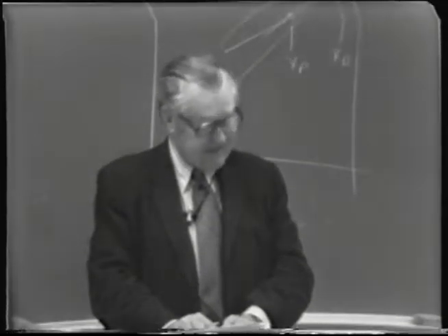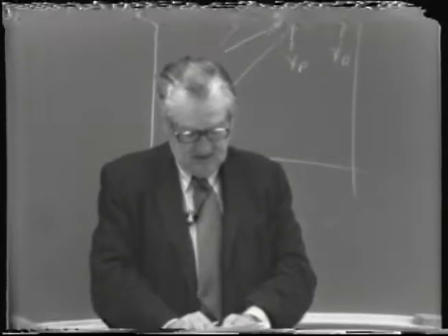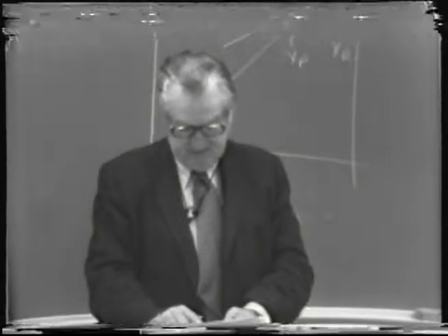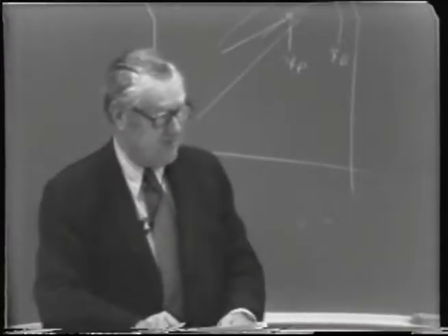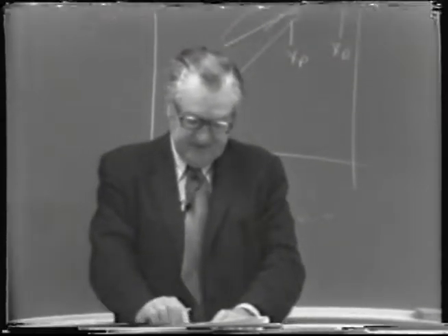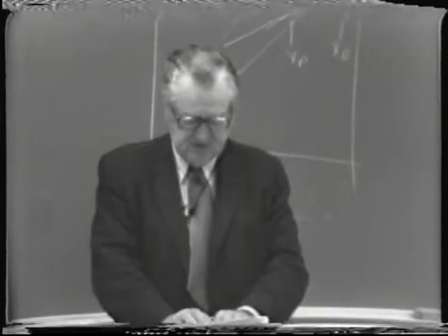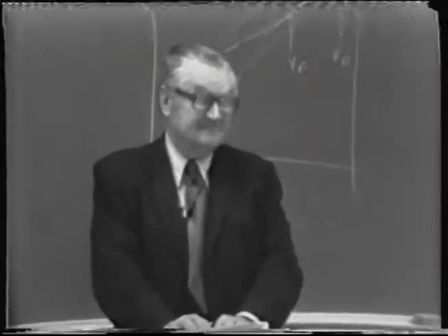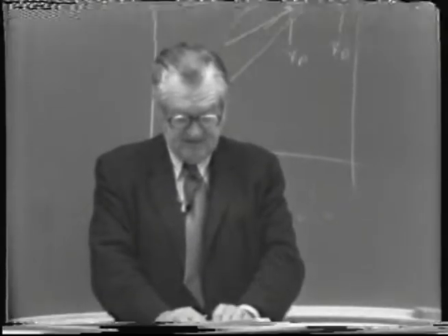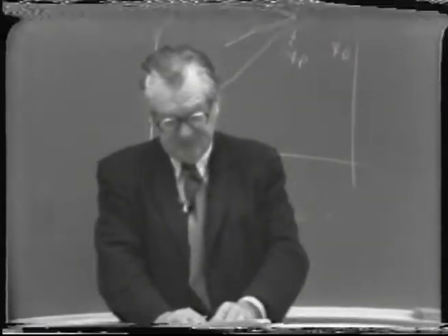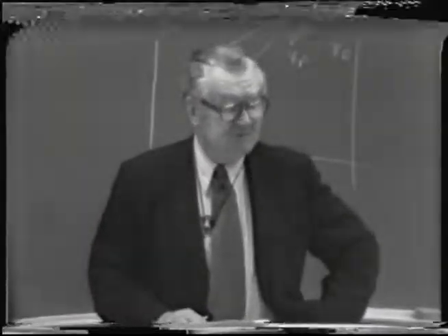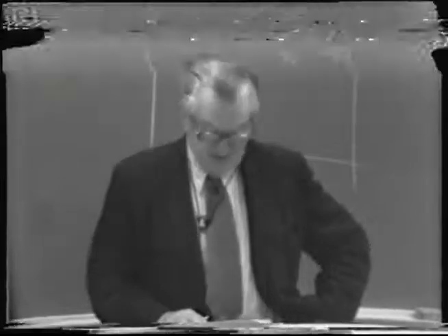Well, 1 pound-mole of a gas occupies 359 cubic feet at standard temperature and pressure, or namely 32 degrees Fahrenheit and 1 atmosphere pressure. Now, if we assume that the pressure change is negligible, but that the volume occupied is that which we would calculate assuming a perfect gas, which I said is a reasonable assumption at low pressures like atmospheric pressure.